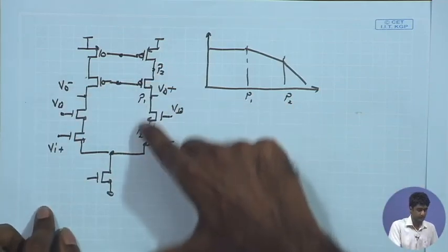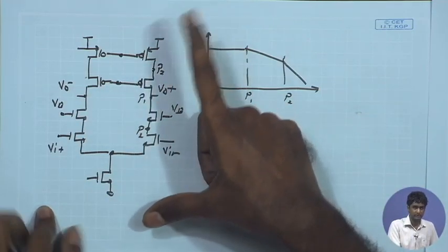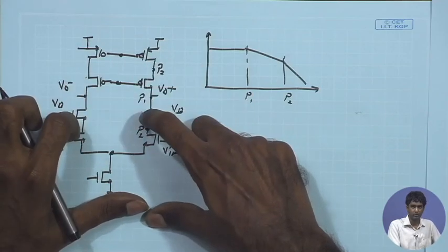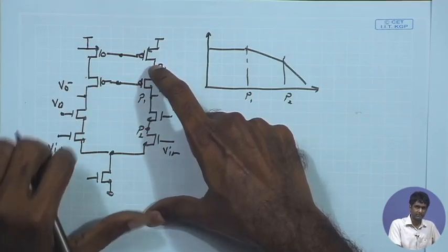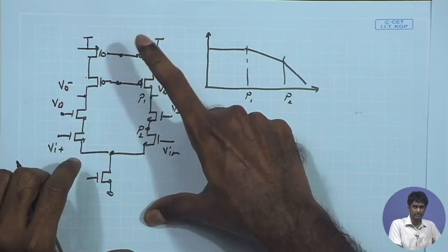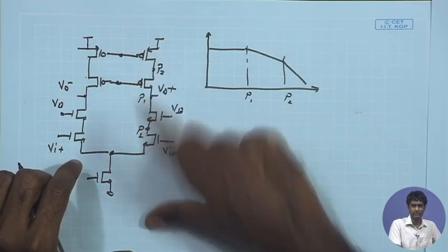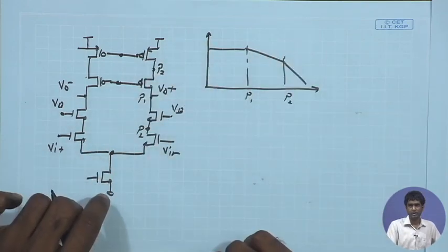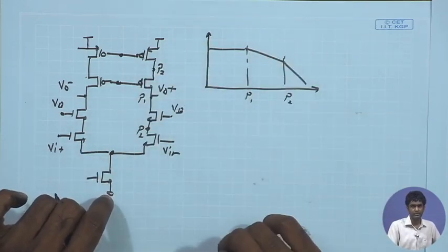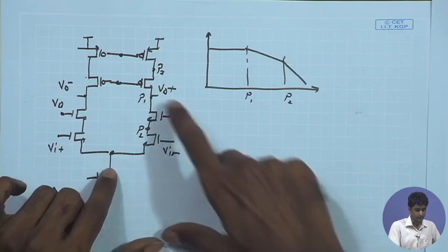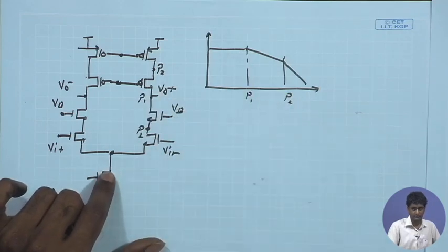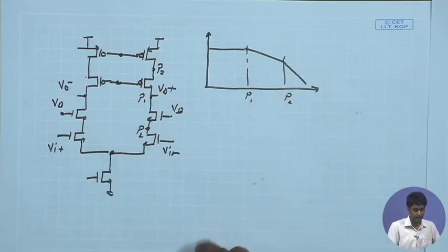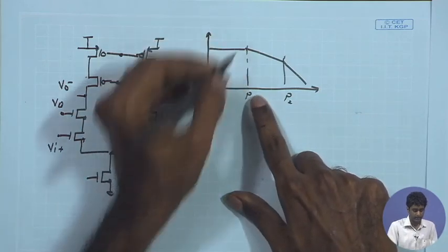They are going to be relatively close, because what we discussed over here, the impedances at these points are almost similar, and as a result the capacitances are also similar because they are coming from the parasitics of the devices. I don't have any additional capacitance put over here. So these 2 points are going to have similar poles in the overall response, and so I can just put them as P1 and P2, and then I can look at the ratio.